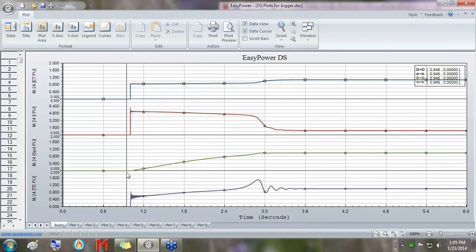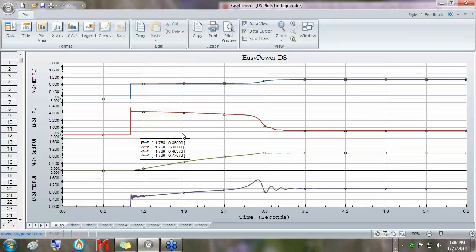And we can see that in this motor starting we have a current of somewhere around 5.1785 per unit. Notice I'm getting that from this little data tool that I can drag over the data cursor here. It's this option here; you can turn it off, turn it on. And the red line is showing us about 5.3 per unit current.